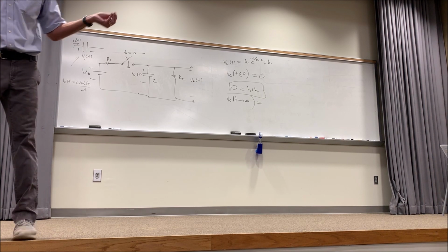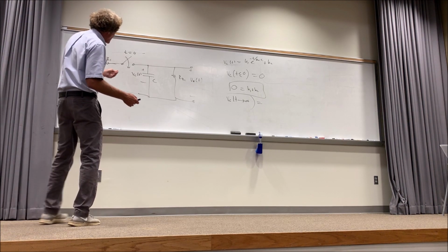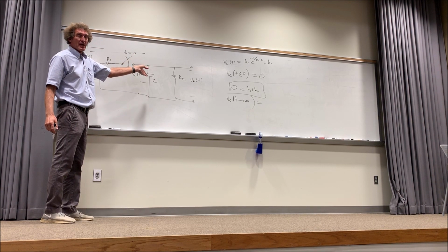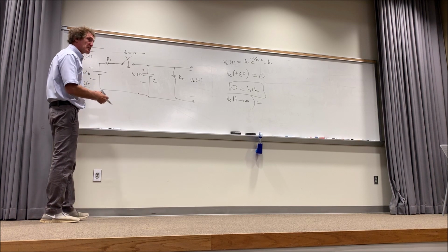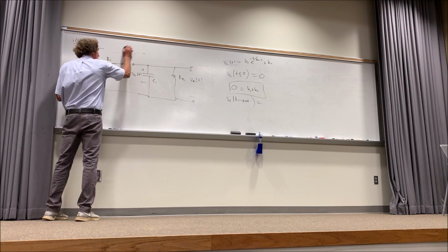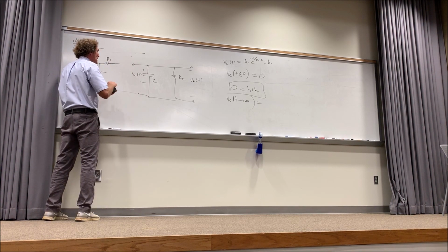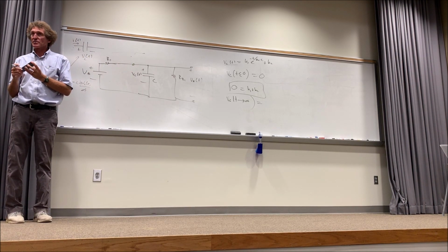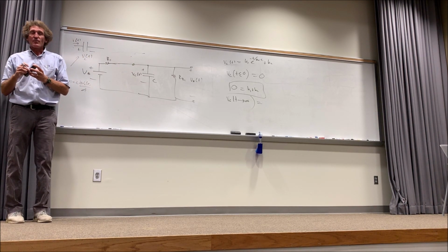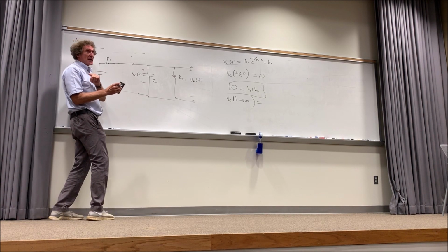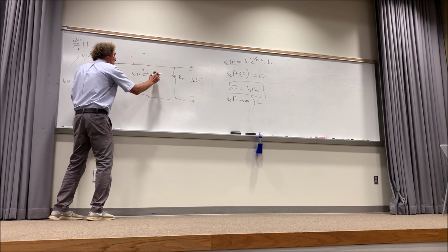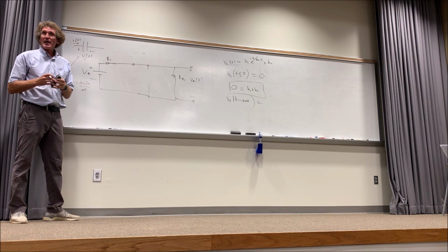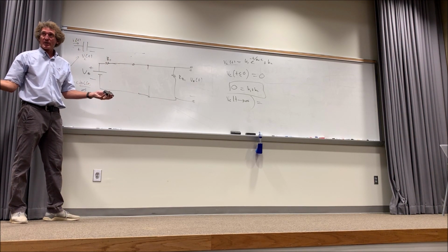However, what happens is this. This thing fundamentally looks like an open circuit at t equal infinity. Can you all see that? Now, for t greater than 0, what happens is this. This is for t greater than 0. It looks like this. Do you all see that, class? The switch closes. For t greater than 0, that's what it is. When t goes to infinity, you might as well just disconnect that capacitor. Do y'all understand that? It looks like an open circuit.